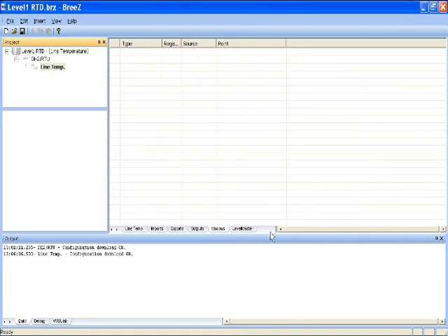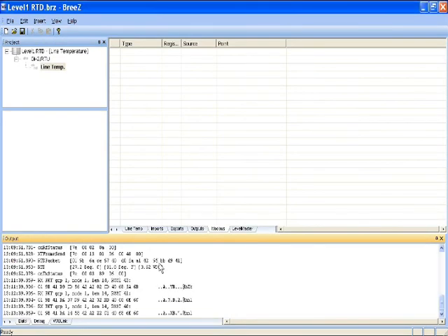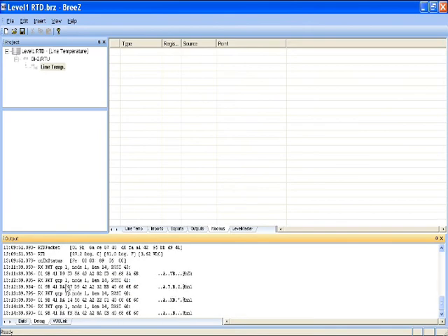Now we can remove our configuration cable from the RTD transmitter and put it back into the configuration port of the DH2. Put your output window in the Debug tab, and here you can monitor all transmissions that come in from the end node RTD transmitter. See our RX packet Group 1 Node 1 length 14 with an RSSI value of 43, and that is happening every 1 minute, exactly as we configured it in the transmitter.